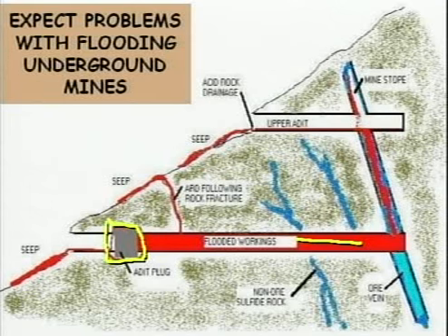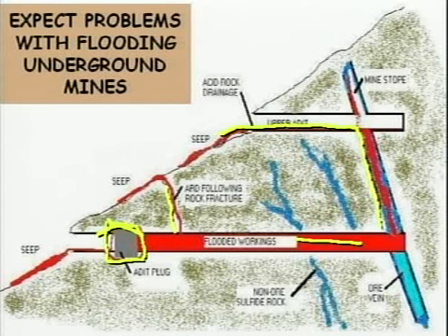As the mine workings fill with water behind an engineered plug, a number of potential problems can surface, especially uncontrolled leaks through fractures and leakage higher up and around the plug itself. A hydraulic analysis is needed to determine the most likely spill points that might develop as the mine plugs, where it could flow out and escape. Seasonal fluctuations in the mine pool may also cause problems with the wetting and drying of ARD-prone wall rocks.